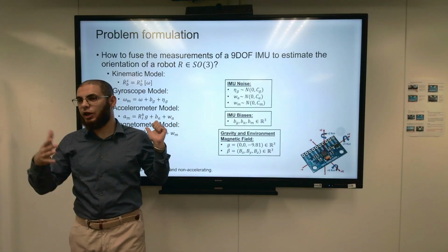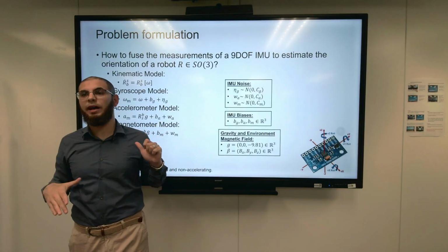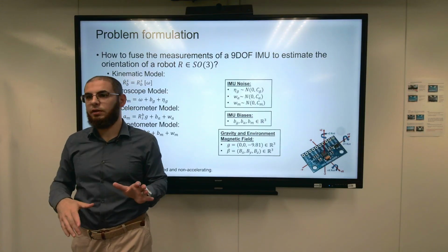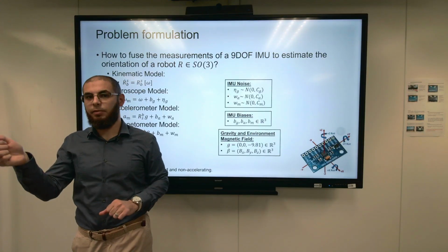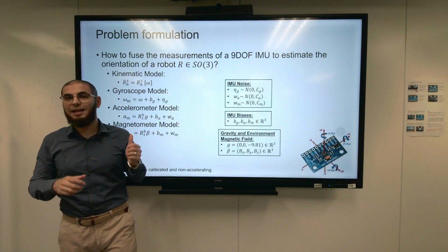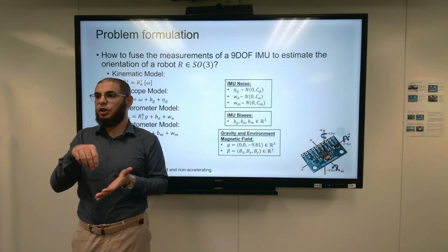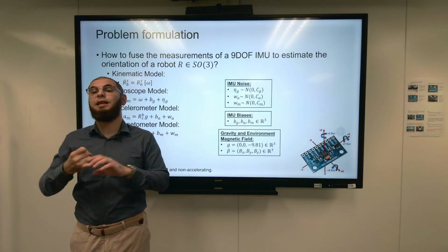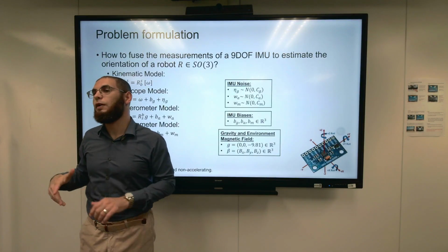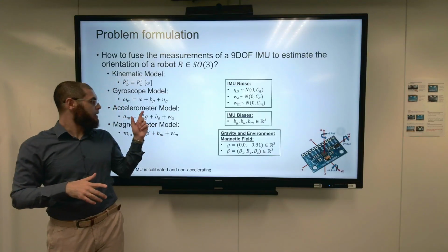That's exactly what we did earlier. If you remember when we had the gyroscope calibration, we were removing the bias by just putting the gyroscope on the table, computing for some time, and taking the average of that. That removes only the static bias. If you go back to the slides when we discussed the IMU, we said that the bias of the gyroscope depends on more stuff. For example, temperature. It depends on acceleration. It depends on more effects. So in real life, the bias here we don't know.